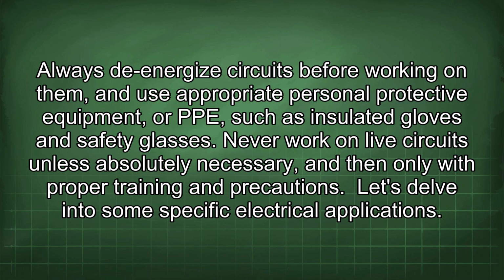Electrical safety is paramount in all electrical work. Always de-energize circuits before working on them and use appropriate personal protective equipment, or PPE, such as insulated gloves and safety glasses. Never work on live circuits unless absolutely necessary, and then only with proper training and precautions.